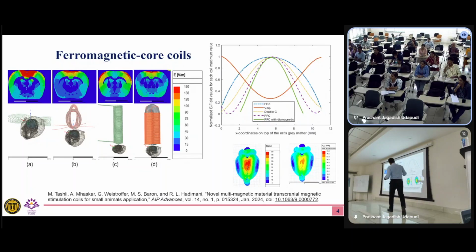We know a ferromagnetic core, if there is a small field, it goes through the ferromagnetic material, and the magnetization of the ferromagnetic material goes up, right? What's a diamagnet? Opposite to, yeah, it repels the magnetic fields, right? So if you put a diamagnetic material surrounding this, it will deflect all the unwanted field.